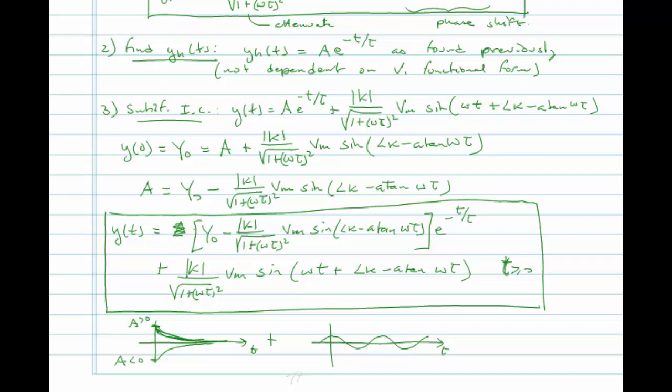Okay, so I think I can stop here and make sure that we've covered everything. What we've done is we've considered finding the complete response of a linear system that's described by its transfer function, and we looked at the case specifically of a sinusoidal excitation. We used the transfer function's magnitude and angle to determine the steady state response, and we used the transfer function's poles, or the roots of its denominator, to find the form of the natural or transient response.